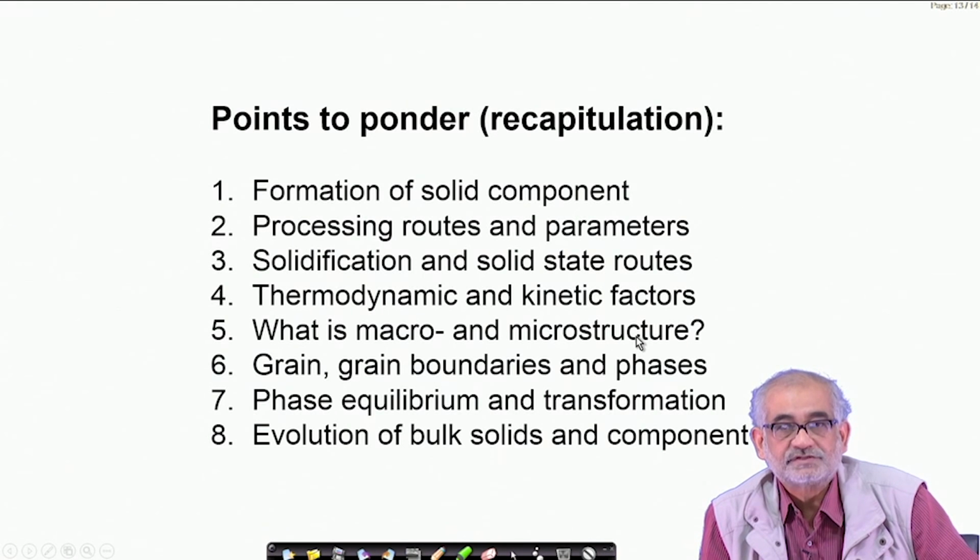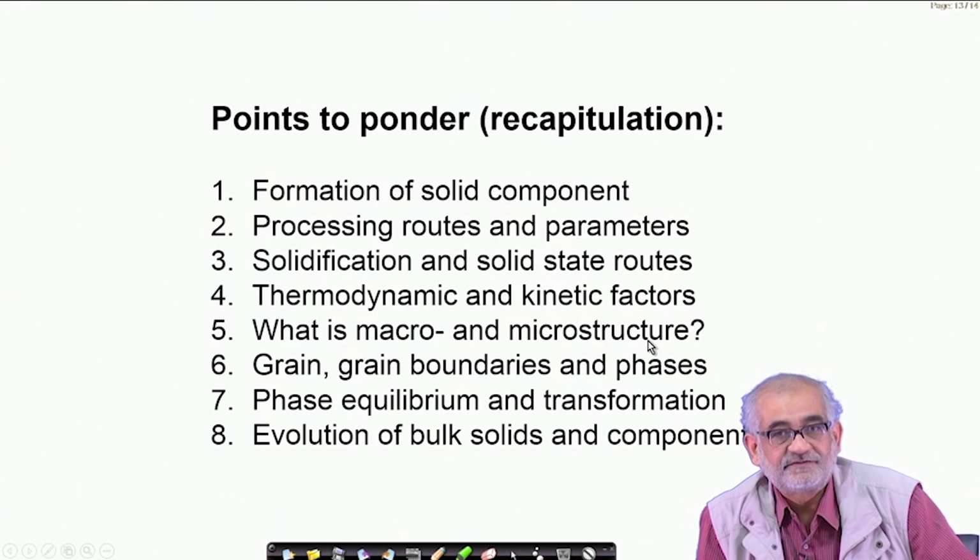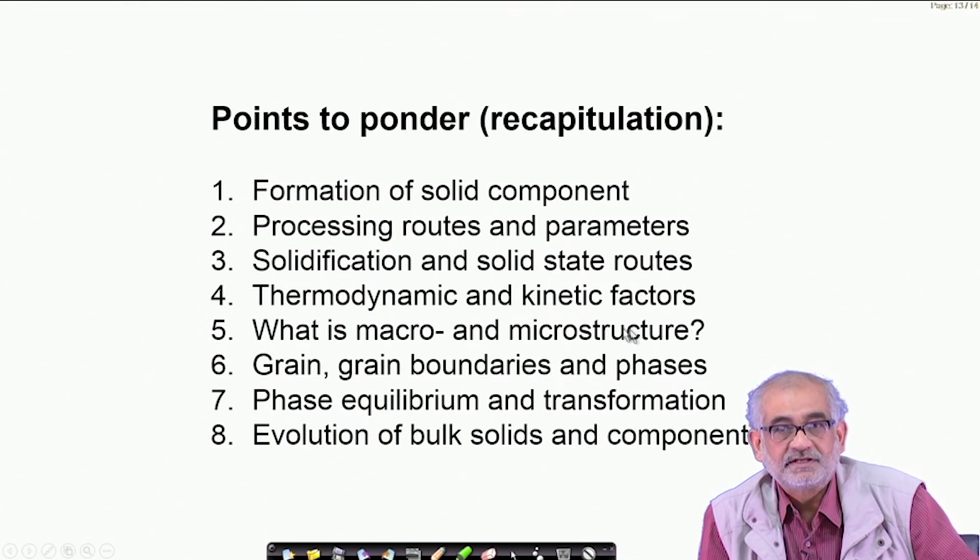When we use an optical microscope or optical illumination, we can reveal up to a certain length scale, and the resolution is up to a certain limit and not beyond. If you want to reveal finer details, then we have to use electromagnetic radiation of shorter wavelength, for example an electron beam, and in such a situation we can see details which are not possible to be seen under an optical microscope.